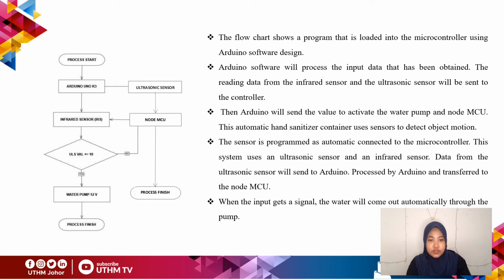The flowchart shows a program that is loaded into the microcontroller using the Arduino software design. The Arduino software will process the input data that has been obtained; the reading data from the infrared sensor and the ultrasonic sensor will be sent to the controller. Then the Arduino will send the value to activate the water pump and NodeMCU.